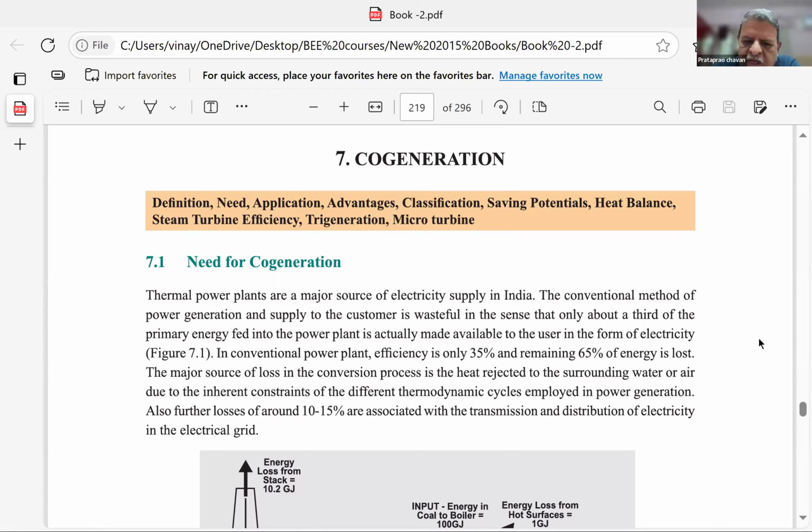So whatever you generate has almost zero raw material cost, only the process cost, establishment cost, that is the capital cost, and the O&M charges. You can generate 3 megawatt, 4 megawatt, 5 megawatts, depending on the volume of raw material available with you. So this generation, which is a secondary generation, is called cogeneration. That is, the factory is co-generating sugar and electricity.